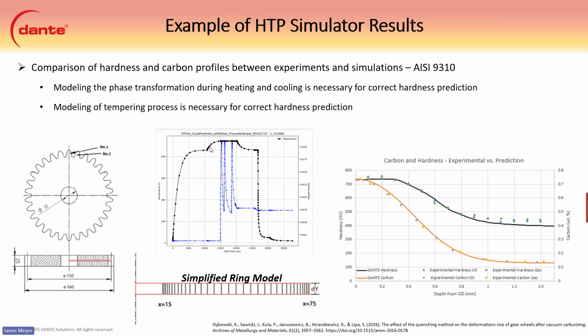It's a heat up and then to austenitize, and then a little bit of ramp up to the low pressure carburization temperature. This uses a 3-step boost and diffuse process that was well defined in the paper, so that's why we used it. And then there's a slight ramp down before quenching, and the quenching is a high pressure gas quench for this application.